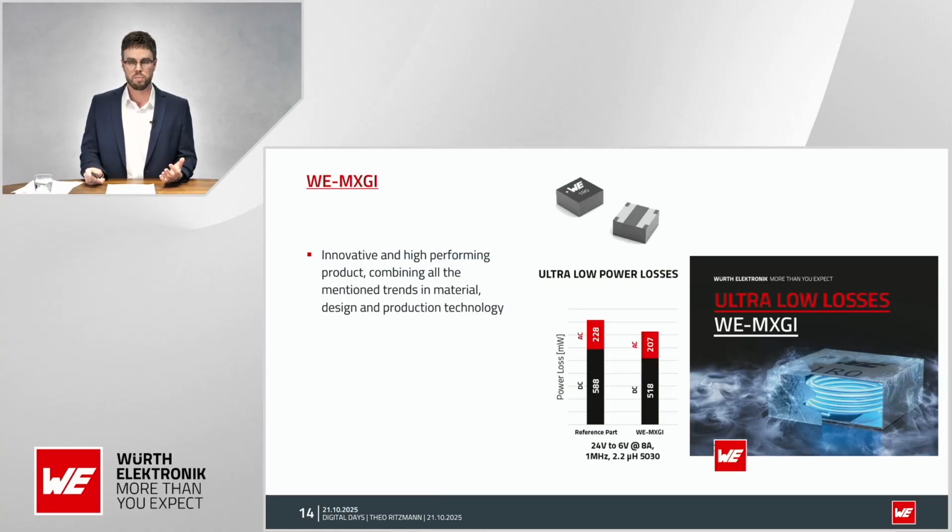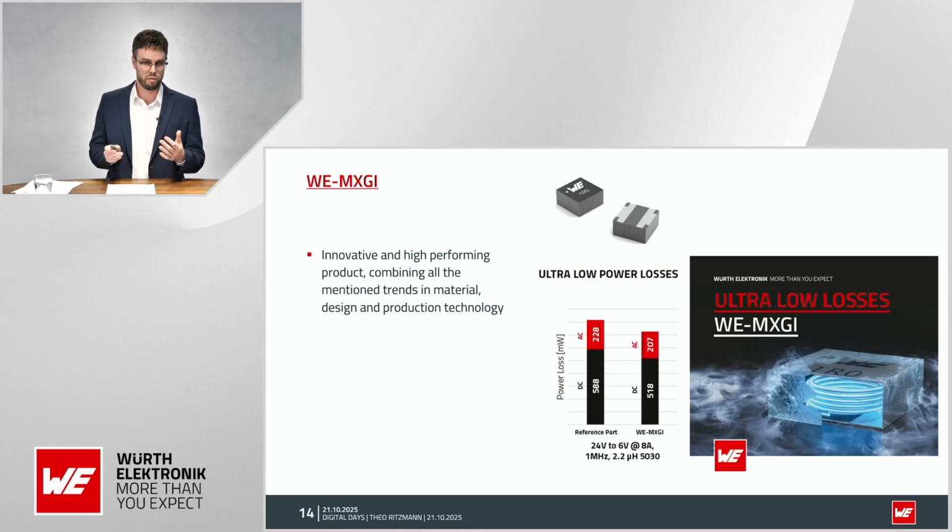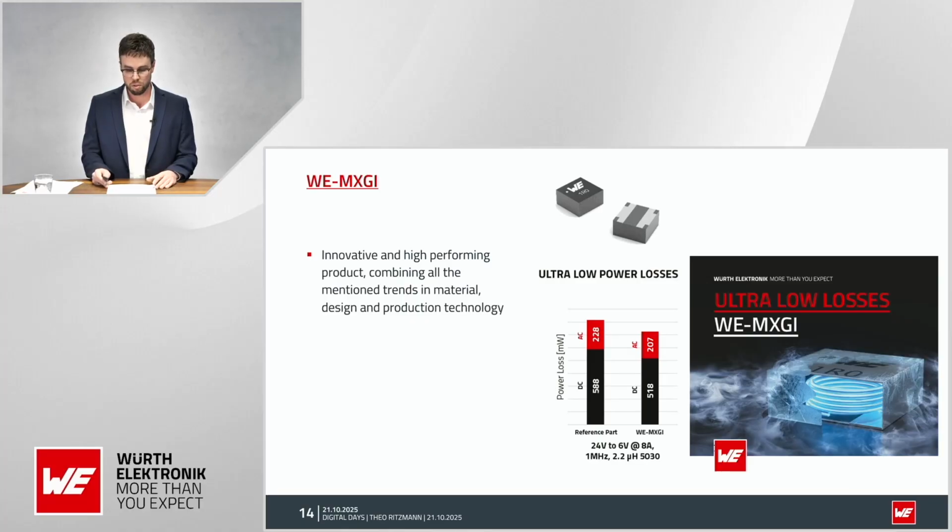And this fits perfectly into the current trend of minimizing the losses. And also a special focus can be set here that the whole design is based on a round wire, which can be seen in the picture here. And this is actually really remarkable because the whole market is pushing into the direction of flat wires as the best choice for low losses. But this achievement was actually possible on a round wire solution.